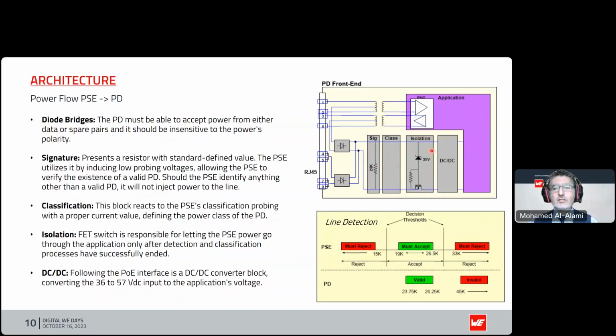Once that voltage is released across, now you have to rectify that. You need a DC-DC, and that's what that DC-DC is there to do, is to take a variable voltage, 36 to 57. I've worked on designs where you can be down to 9 volts, beg your pardon, and up to 72 volts. It very much depends on what auxiliary supply sometimes that you also have that you have to run off. So in this DC-DC, you'll also need to maintain isolation.